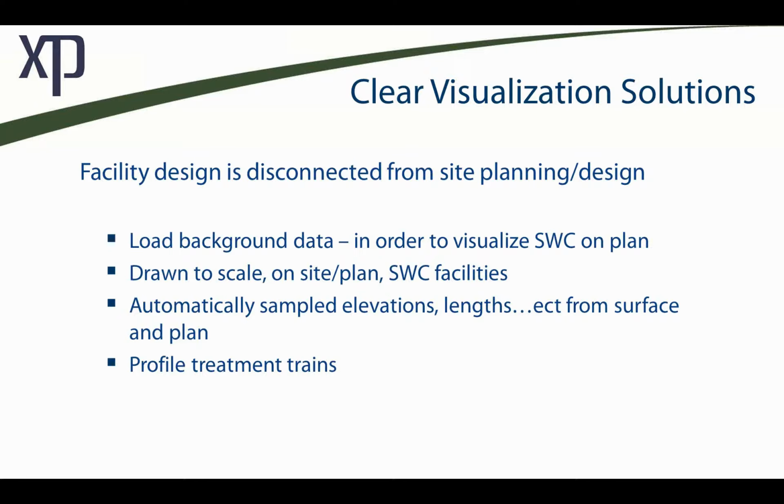So the volume estimates, and we'll see an example of this later if that doesn't make sense just being spoken. But we need to understand how storage is occurring, how infiltration is occurring, and how all the facilities can drain to each other. So that last point, how they drain to each other, the inter-watershed impacts, we have to understand, we have to be able to see in order to really know that our facility is going to work.